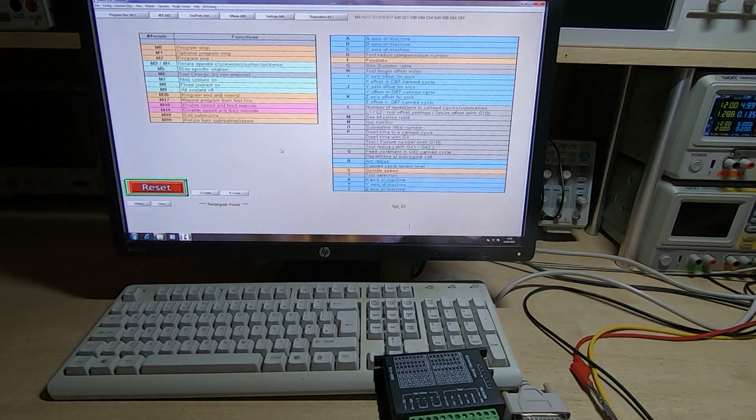If we bring up the M codes, the one that is most pertinent to this video is M6. M6 is the tool change macro. And in particular, you don't know if you can read this, but it says M6 tool change and then in brackets, two macros. And I think this is where the confusion often arises, and I quite often see in forums and discussions on this people asking where to put their modified macro. Does it go in the first macro, the second, or where is it supposed to go?